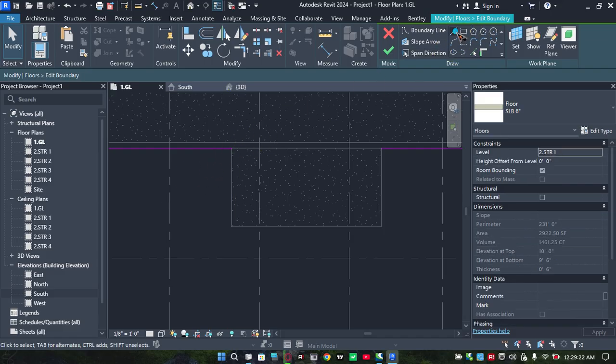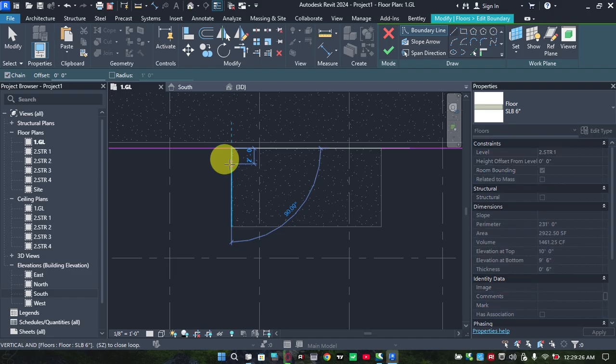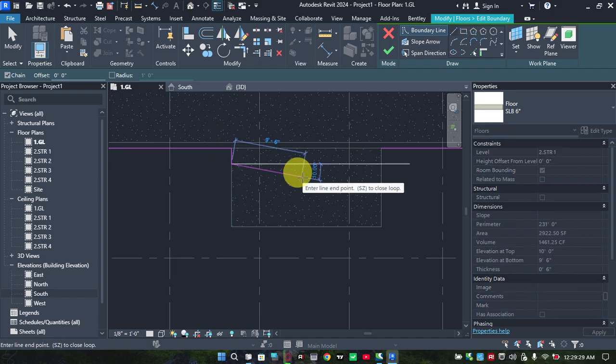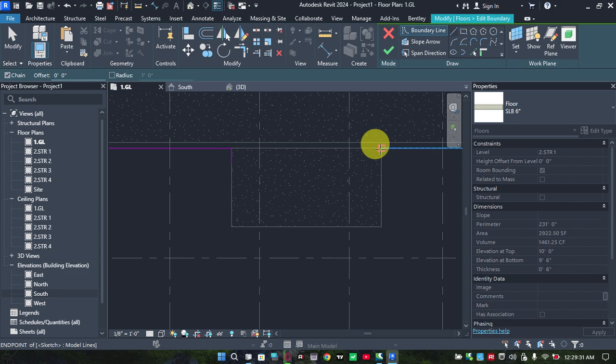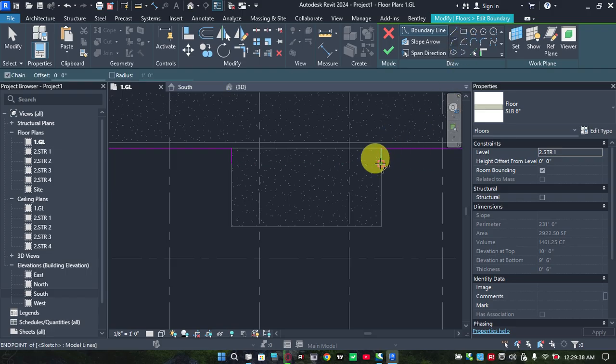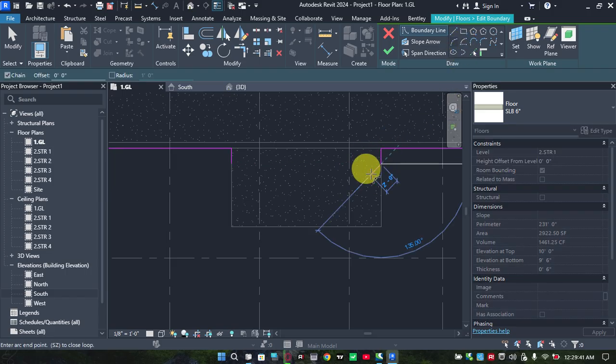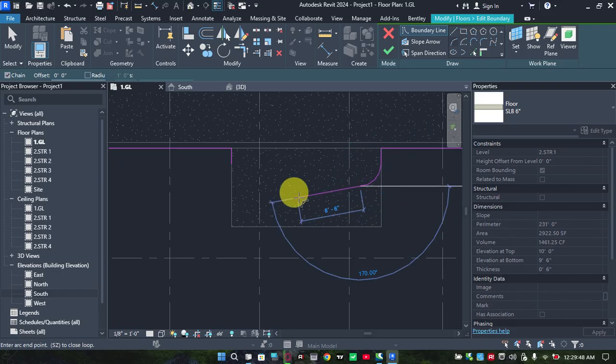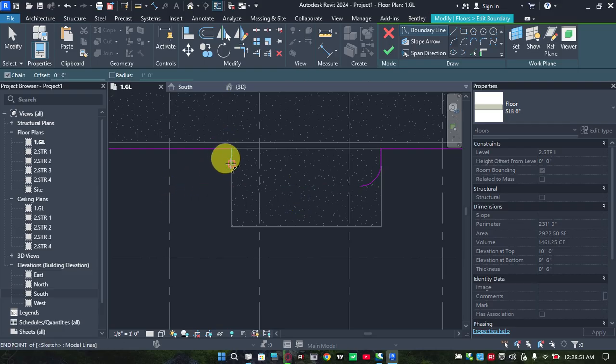Now you pick line, you pick 1 foot, bring out 1 foot. Okay, bring out 2 foot out, bring out another 2 foot out. Yes. Now you pick your connect here, you bring down to 2, you bring it to 4 foot, and yes, you can actually make a curve. The same thing here, you bring it at 45 degree, 4 foot, and you create a very nice curve.